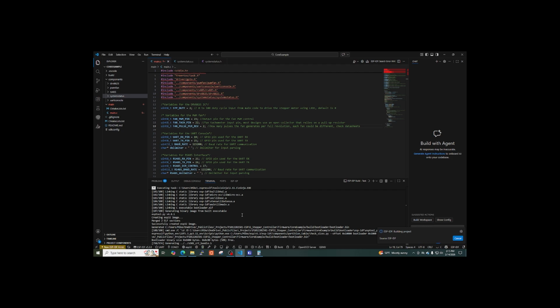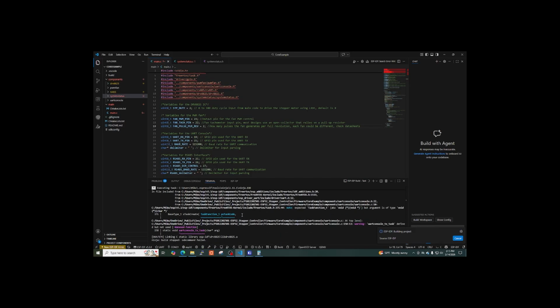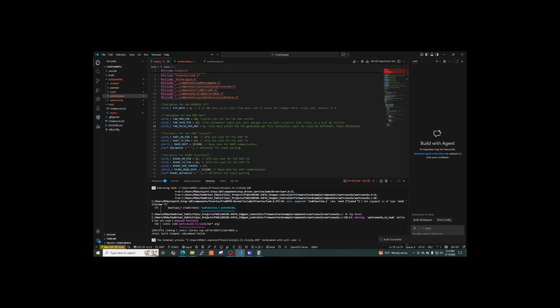If it takes too long to travel from one end to the other, that could indicate an error. We could basically create a status flag for that if we really wanted to. That'd be a matter of timing how long it takes to traverse from one end to the other. The timer would reset at each limit switch.